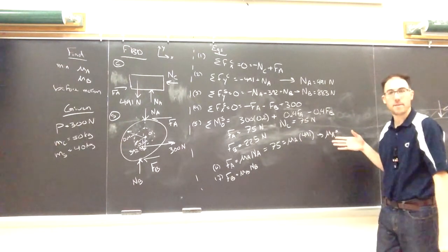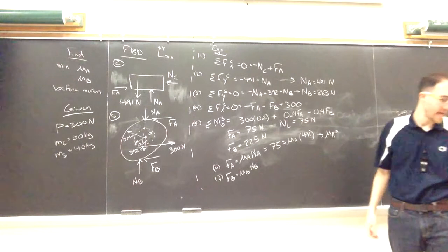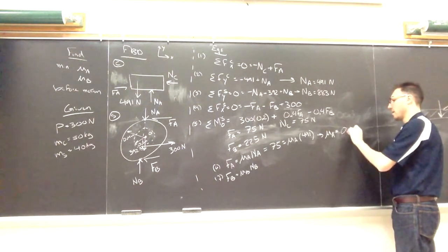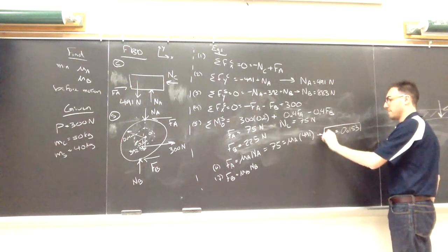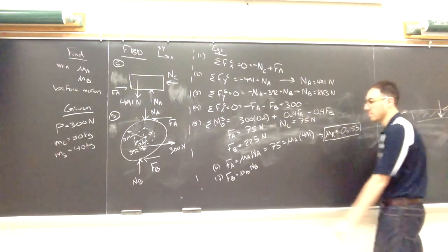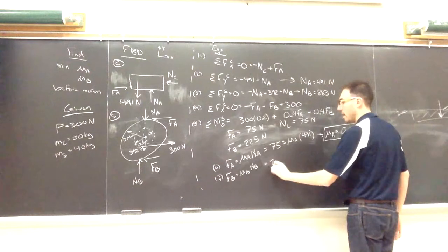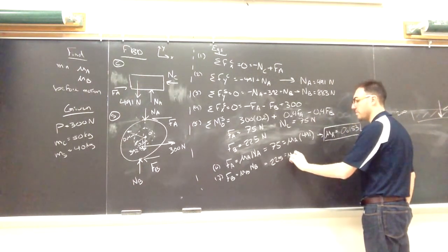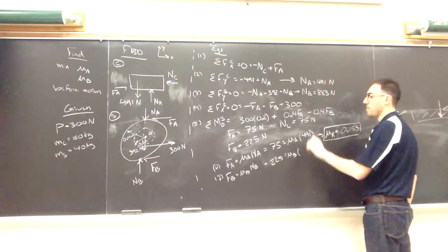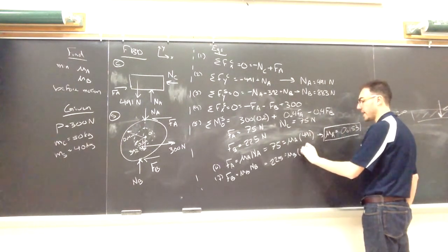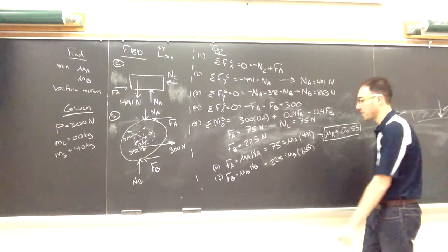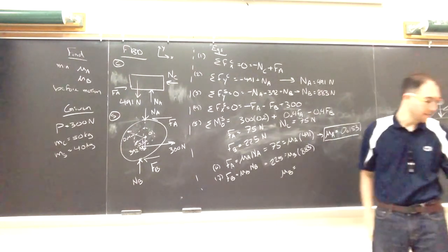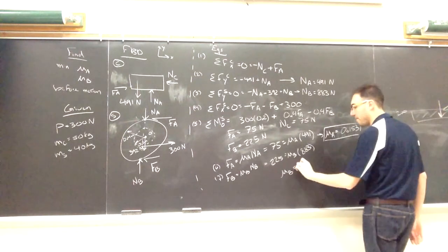So the minimum the coefficient of friction has to be at A, or could be at A, is 0.153. And down here, the friction force was 225 newtons times mu B times the normal force between those surfaces was 883. So from equation 7, the smallest that mu B can be is 0.255.